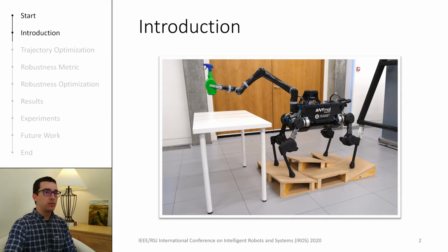And if an unexpected force is applied to the robot, for example the one shown here in yellow, it may cause the robot to deviate from its original plan, possibly leading to failure. One reason for failure could be that when the robot is trying to resist an external force, it tries to use more torque than what its actuators are capable of delivering. Another reason could be that resisting a disturbance would require unrealistic contact forces, or contact forces that would cause slippage given the friction coefficient at the contact points. In unfortunate situations, failure can be due to both these reasons simultaneously.